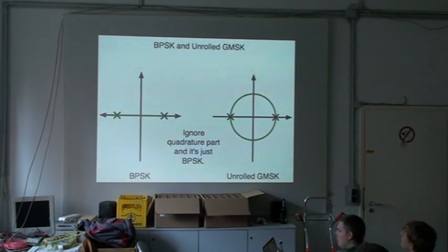And the frequency shift by 1/2 the symbol rate is mathematically very simple. On alternating samples, you just negate one of the components to get your 1/2 symbol rate frequency shift. So on every other symbol you negate the real component, on every other symbol you negate the imaginary component. The computation associated with these frequency shifts is very simple because you're negating samples in a regular pattern.